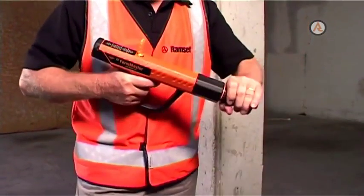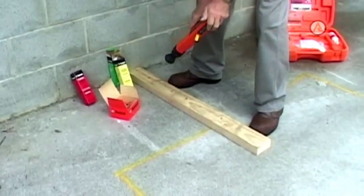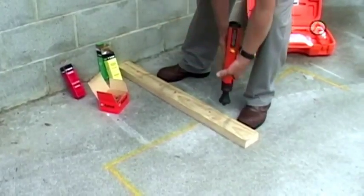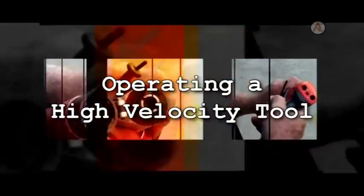With this tool, the spent power load is removed from the tool automatically as part of the opening and closing sequence. The opening of the tool resets the power load index lever and the strip is lifted by the closing of the tool, bringing a fresh power load to the chamber. Operating a high-velocity tool.